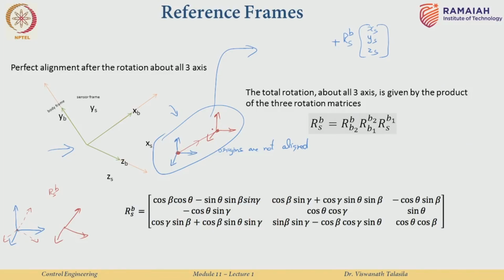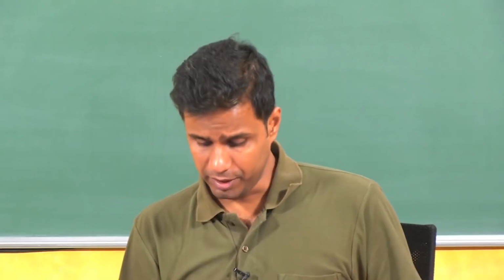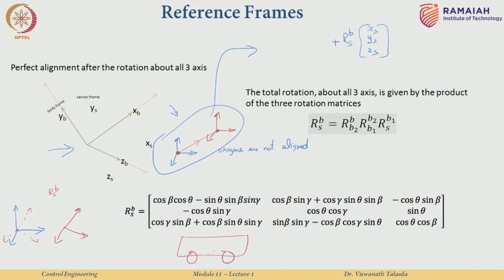Now, let us not worry how that is actually calculated. Let us say someone actually tells you by measurement. So, you have your car and this is the center of gravity, in some x, y, z body position origin, and you have placed your IMU over here. You can physically just measure it, right. So, you know that this is some x1, y1, z1 where you have placed your sensor, and you know the difference between x and x1, between y and y1, z and z1.